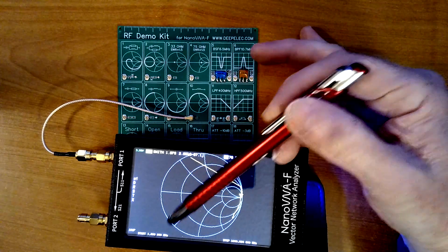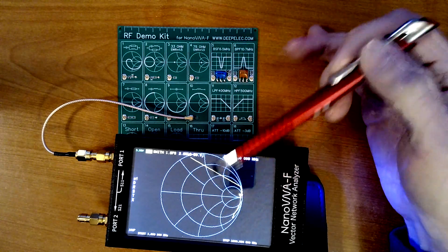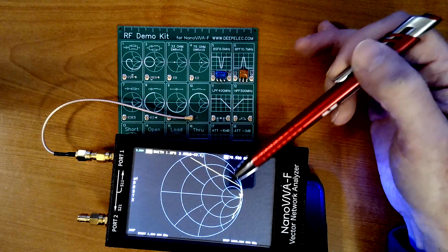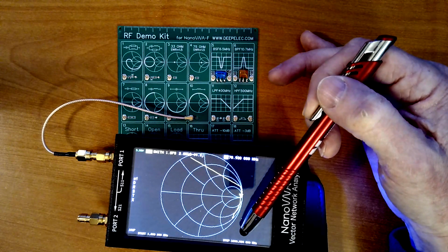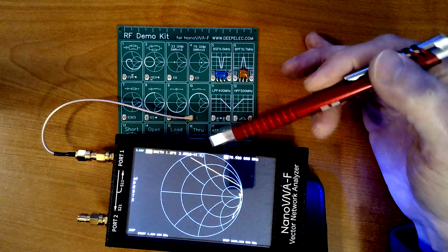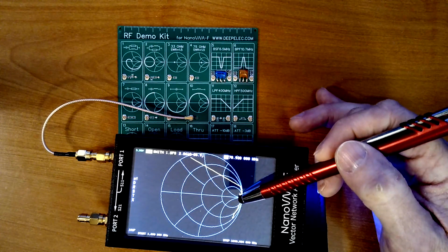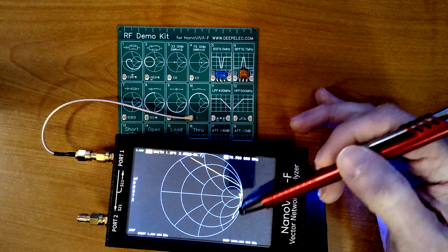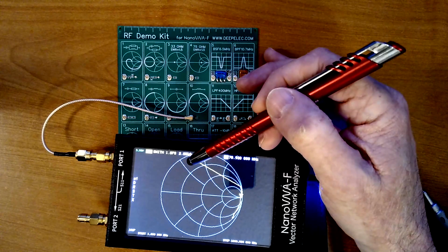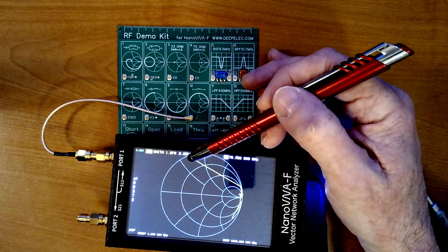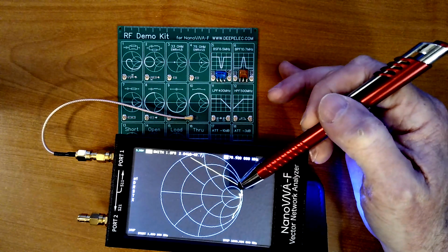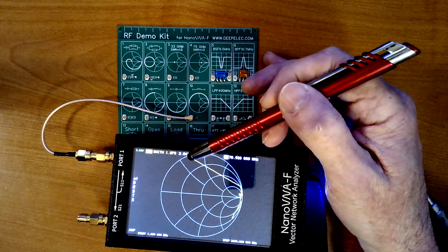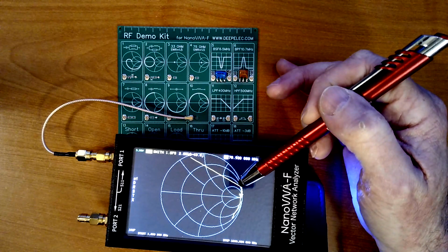Instead of going from 1 megahertz to 1 gigahertz, if we went from 1 megahertz to, say, 30 megahertz, it might look like this. But because we're going to 1 gigahertz, two things happen. Number one, we do hit the self-resonant frequency, and then beyond that, it looks capacitive, as shown in our model. However, it also has this weird line here. That's just because this is 1 megahertz, and this is 2 megahertz over here, and then we go on up. And so there were no points taken between 1 and 2,